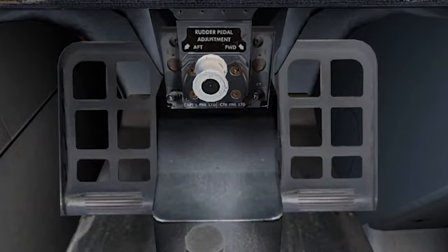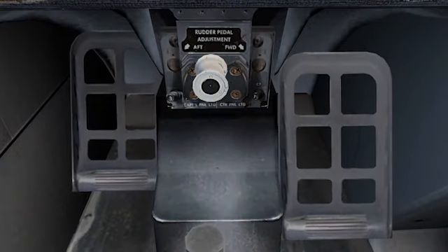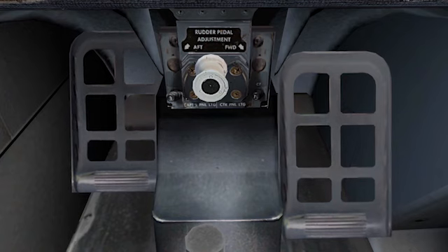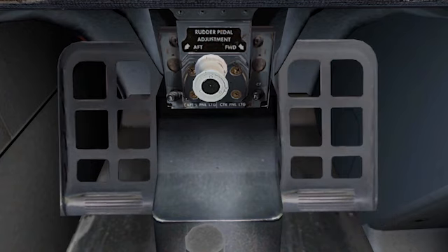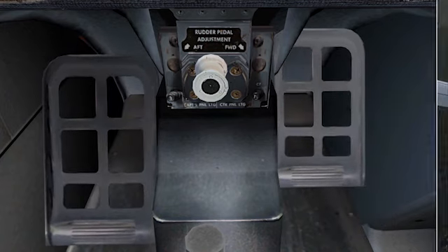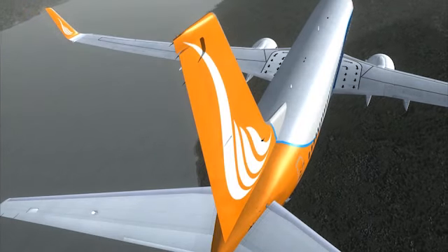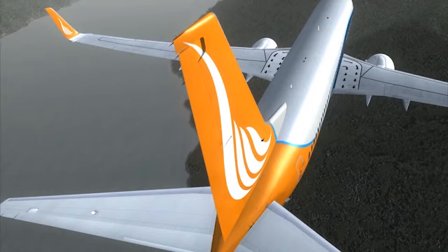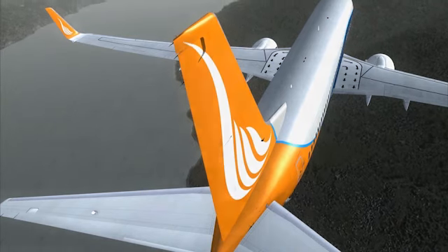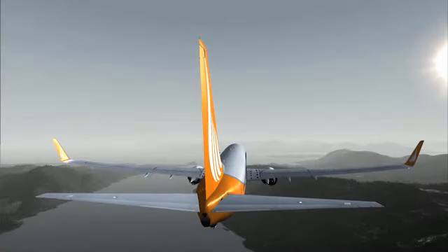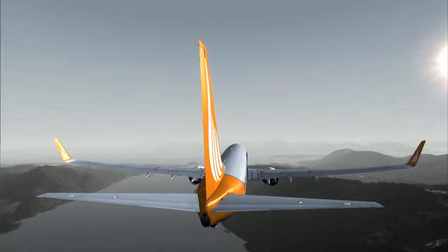During manual operation, the pilot presses the pedals to achieve movement in the respective direction. For example, when the right rudder pedal is pressed, the rudder moves to the right of its neutral position, thus creating a rightward turning moment and achieving yaw to the right. The same logic applies when the left rudder pedals are pressed.